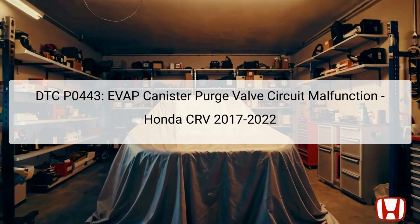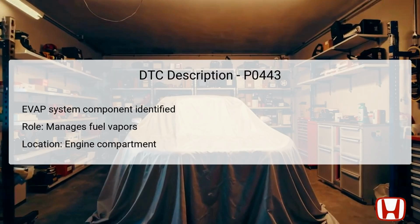It's usually located in the engine compartment connected to the EVAP system, and a malfunction here may lead to failed emissions tests or increased emissions. Understanding this DTC is essential for resolving any underlying issues affecting the vehicle's performance or compliance with environmental regulations. DTC P0443 indicates a malfunction in the EVAP canister purge valve circuit, specifically indicating that there might be a failure in the valve's operation or its associated circuitry.